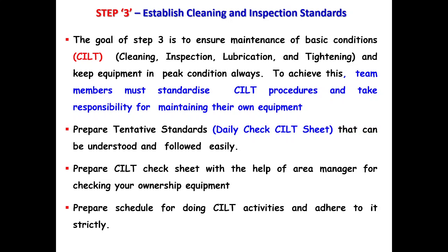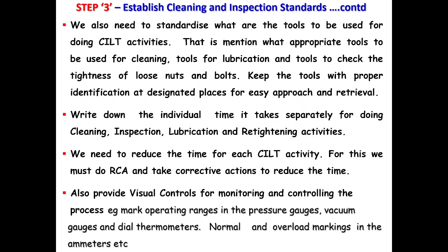Prepare the CILT check sheet with the help of the shift in-charge or area manager for checking your own equipment. Prepare a time schedule for doing CILT activities and adhere to it strictly. We must also standardize the tools to be used for doing CILT activities safely. That is, appropriate tools for cleaning, tools for lubrication, and tools for checking the tightness of loose nuts and bolts. Keep the tools with proper identification at designated places for easy approach and retrieval.